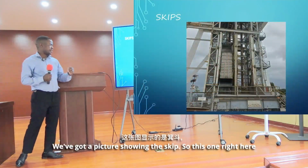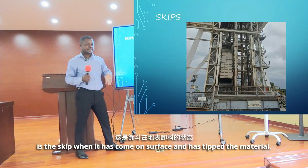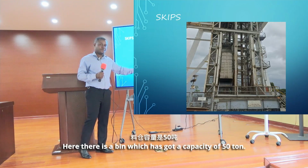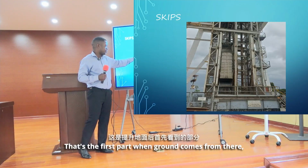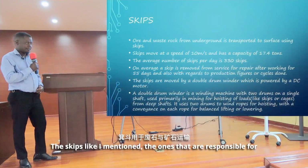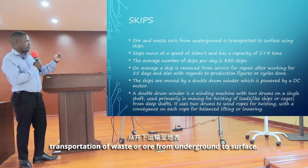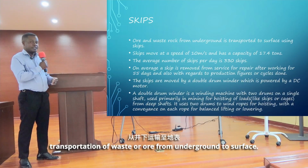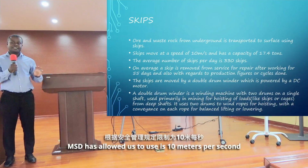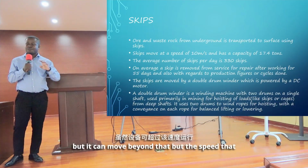We've got a picture showing the skip. This one right here is the skip when it has come to surface and it has tipped the material. Here there is a bin which we call 50 ton, which has a capacity of 50 ton. When ground comes from there, it goes into the 50-ton bin. The skips, like I mentioned, are the ones responsible for transportation of waste or ore from underground to surface. The maximum speed that MSD has allowed us to use is 10 meters per second, but it can move beyond that.